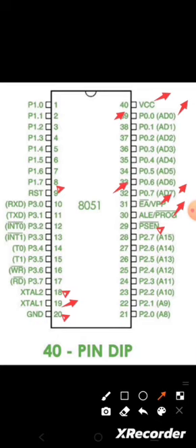32nd are the pins of port 0, and next 1st to 8th refers to the pins of port 1, and next the pins 21 to 28 refer to the port pins of port 2, and next the pin number 10 to 17 refer to the pins of port 3. So totally we have 4 ports. Each port has 8 pins. So 32 IO pins are present in 8051.